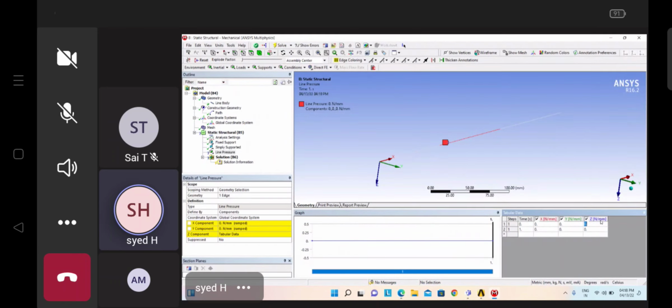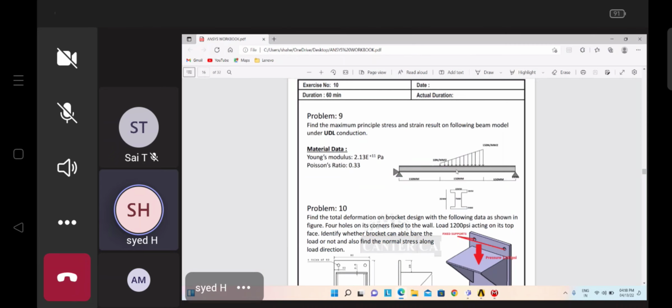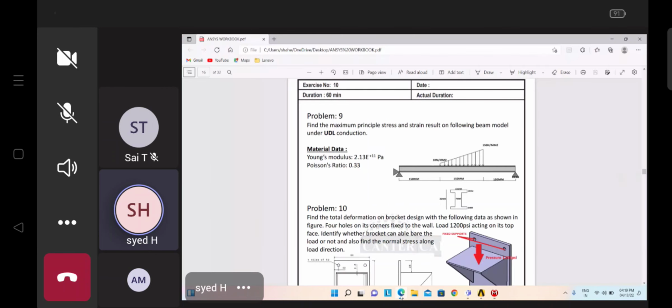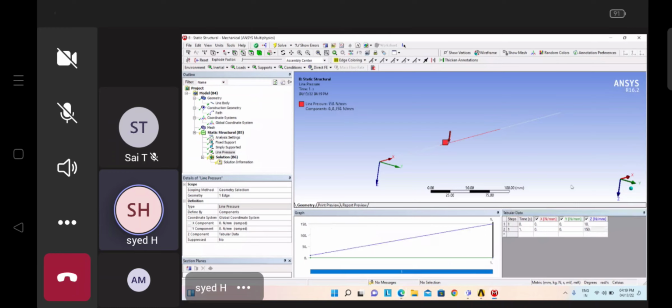Okay, we have taken it wrong. It is not a 1D analysis, it is actually a 2D analysis, because mm square means area, and area requires a complete surface. Here it is showing mm only. So we will take initially 10 only, and the maximum load it is assigning is 150 Newton per mm square. Okay. Now we have specified the uniformly distributed load.